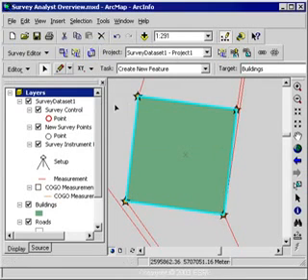Once I perform this transformation, you'll notice the building has actually been moved in coordinate space. The building moved to the surveyed point. Also, you'll notice the symbol changed. The symbol now is a yellow star. So that symbology for linking and snapping is entirely up to the user. I specified this so I can see the difference.